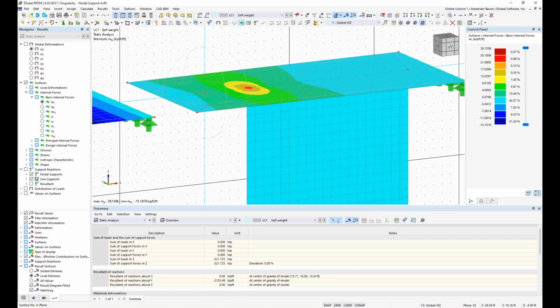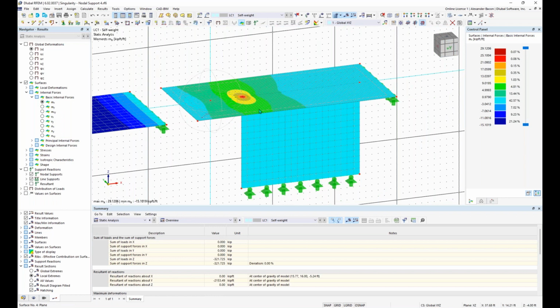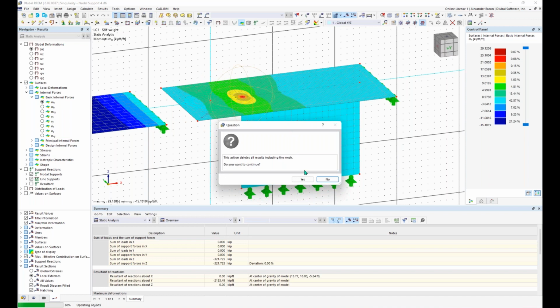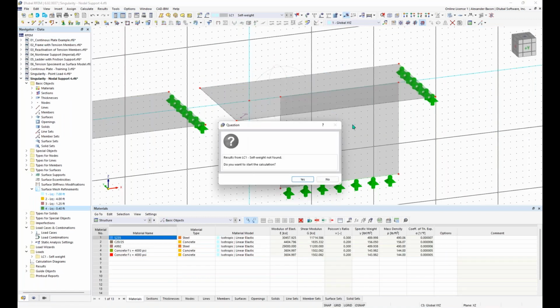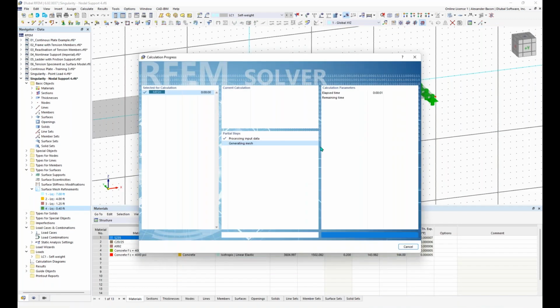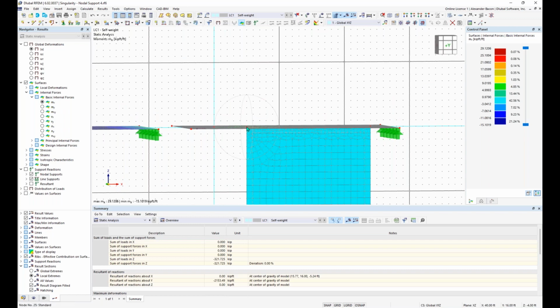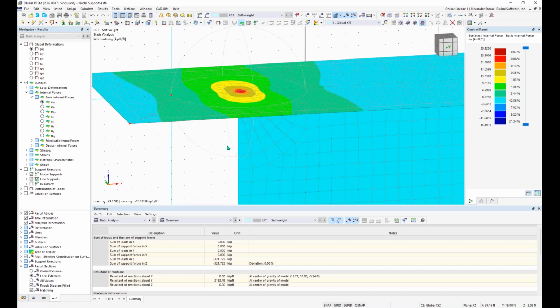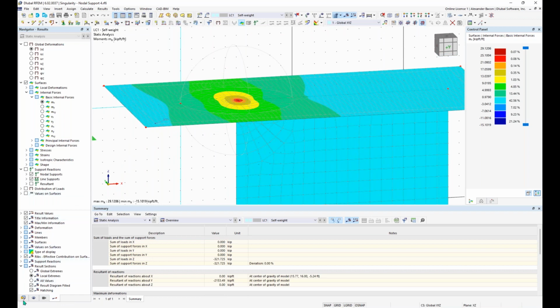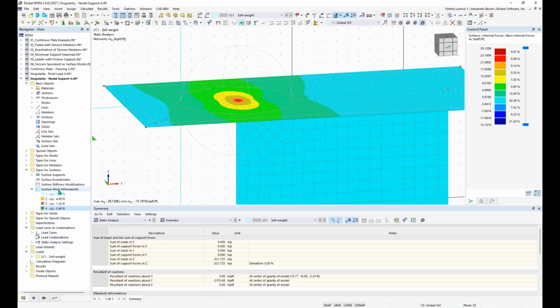So when I talk about corners of walls, you want to watch out for this, and what you can do is, adding an FE mesh refinement like this would help, but it would also help to just make the corner of this wall rounded just a little bit, so it's not just one single point feeding into an FE mesh node like that. And then also we have regions, smoothing regions that you can apply to your surfaces here as well.